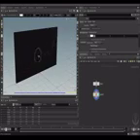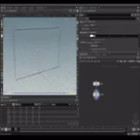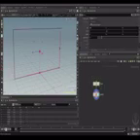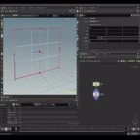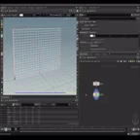And it's not working yet, and this is because this brush is painting points or primitives. But if I press W, you'll see that we don't have any points or primitive in the middle of this box. So let's add more geometry by going here, and let's change this to polygon mesh. And I can say I want, for example, 5, 20, 20. Let's go back to our paint sub.